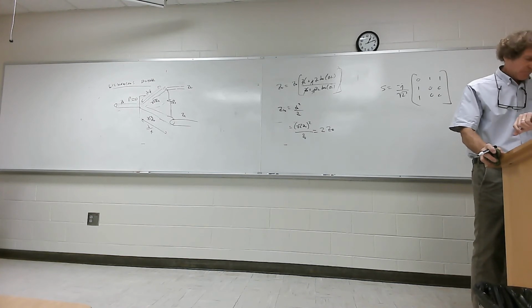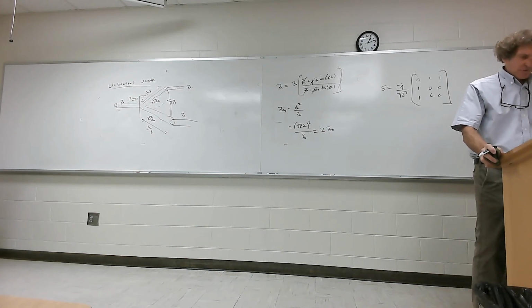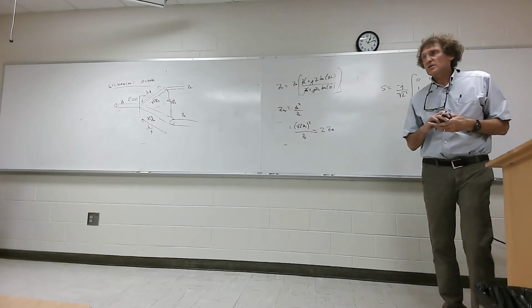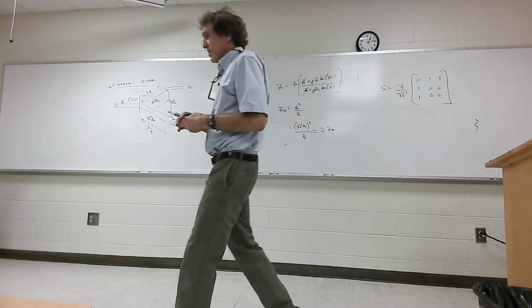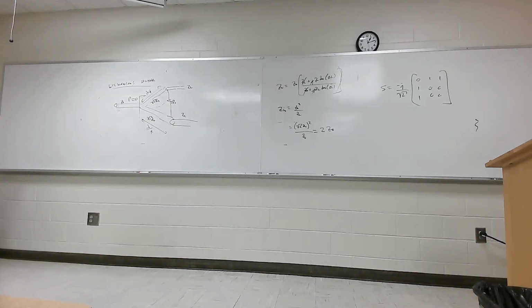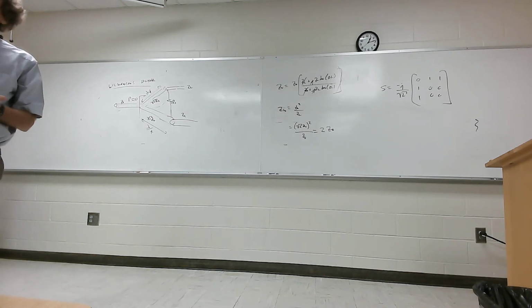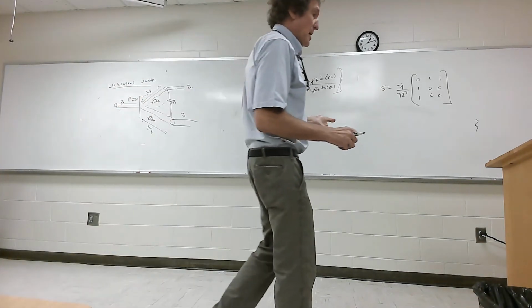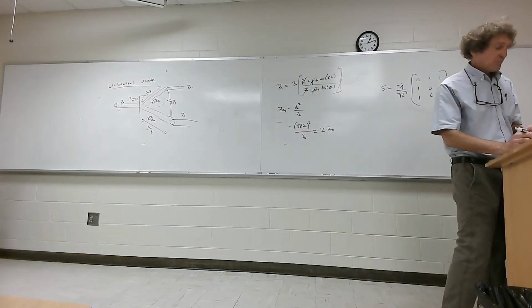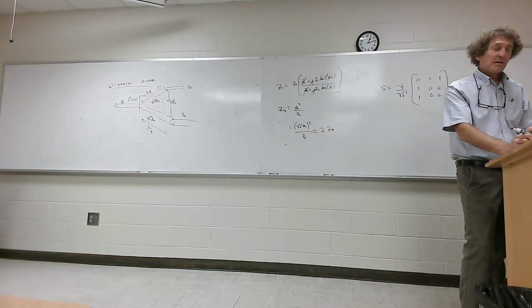I'm going to mention something about 4-port circuits. You can have any number of ports. 3- and 4-port circuits are usually used for telecommunication work and for radar work. I'm not going to spend too much time on this. Do you remember how we had a circulator, with some power going into one port and launched, and anything coming back through that port was redirected to another port? That's the most common thing you see with radar. But in radar they will also use circuits with 4 ports.